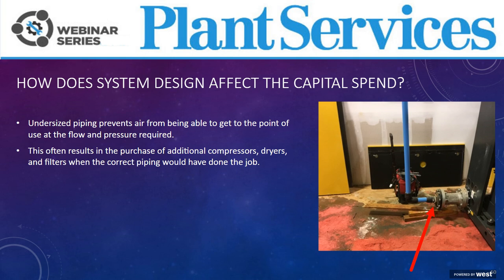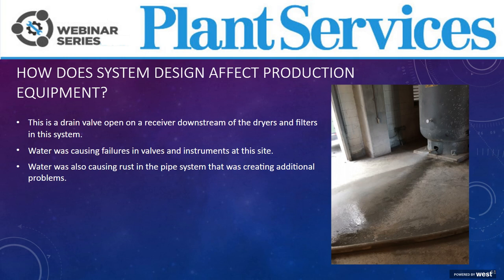If they had correctly sized the pipe, they could have saved about $600,000 in capital and almost $300,000 in maintenance expense on that $600,000 capital spend for compressors. So it's really important to do the right design in the beginning so that you don't spend capital you don't need. Another thing that happens with poorly designed systems is that you wind up hurting your production equipment.